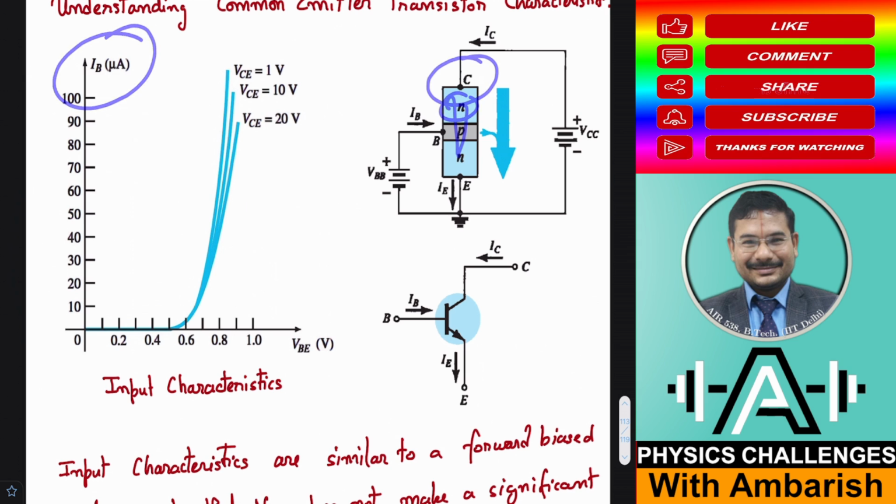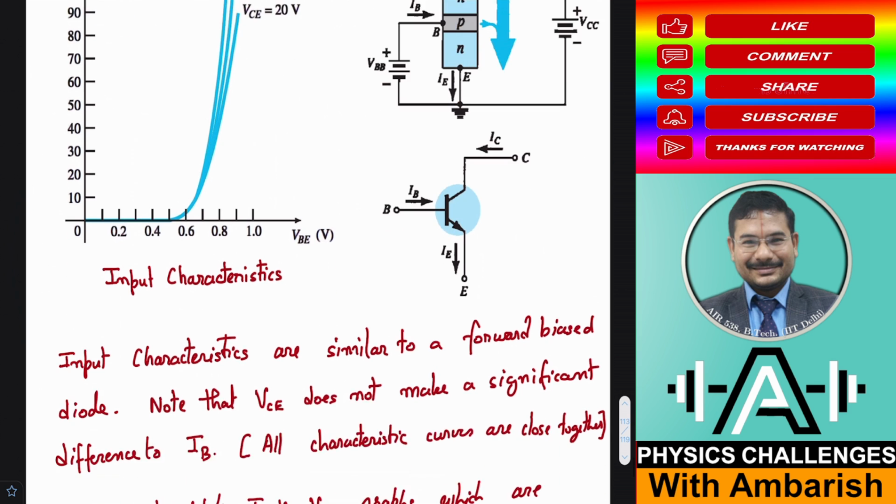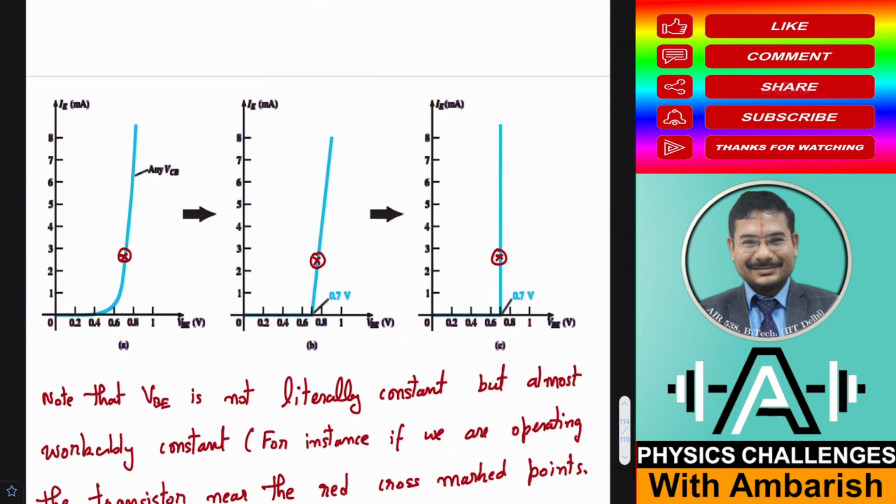That's why this is in microampere, but the collector current is going to be in milliampere, which will be almost equal to the emitter current. Okay. And emitter current is also going to be in milliampere. So I can also plot the emitter current versus the base emitter voltage. This is supposed to be VBE. Okay. Emitter current versus VBE I can plot, and this is the actual curve, actual diode kind of behavior.